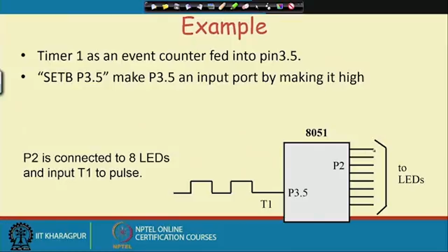You can connect something like this, maybe put a resistor, then put one LED here, put an LED here. This way for each of them we can have a current limiting resistance followed by some LED, so for every point we can connect one. So, 8 such LEDs can be connected. It will have a nice display of the pattern of the number of pulses that are received in this T1 bit.